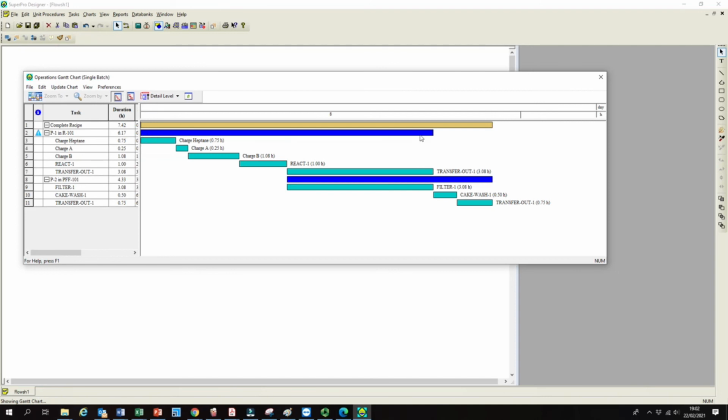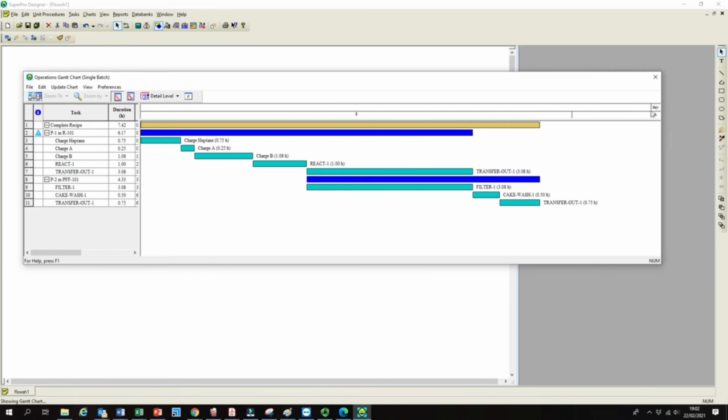So you finish the batch process. We manufacture the product C roughly in 8 and then plus a few more hours, so it's good. Reaction happens for 1 hour, charging of B happens for 1 hour, charging of A takes 0.25 hours, and you manage to charge 1200 liters of heptane in 0.75 hours. Whenever we talk about a batch process, normally in the textbook we see A plus B giving rise to product C, that's my kinetic constant, tell me what's the order of the reaction. Probably you might be used to those type of things, but in engineering, time really matters.